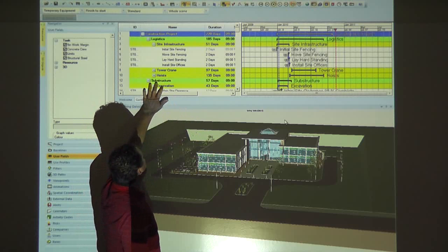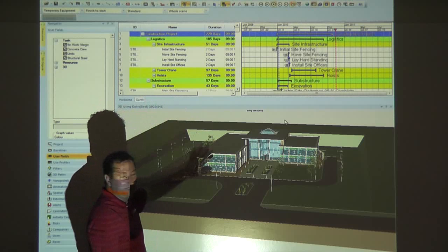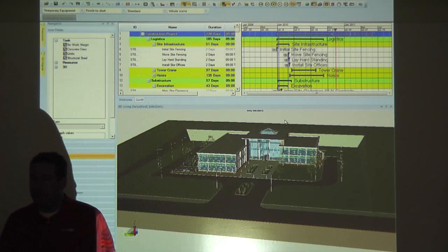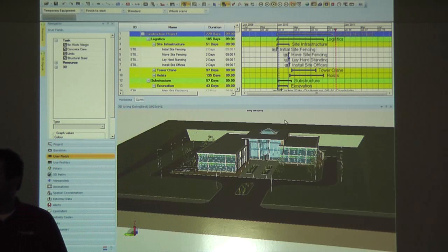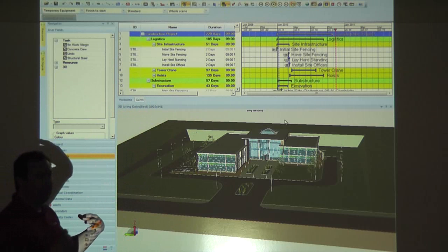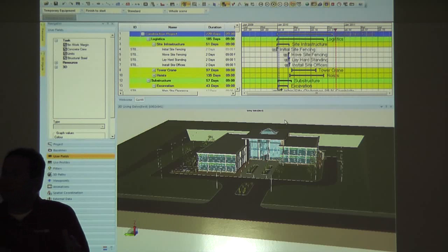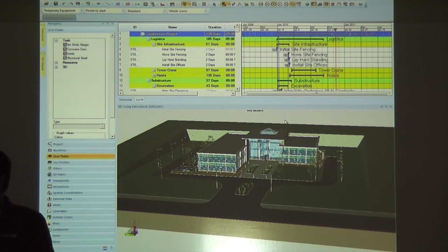The task list would come from SDS2 because inside of SDS2 I would have brought a Microsoft Project task list in and said these columns are sequence 1 columns. So I would go to my task list and say these columns are sequence 1 and then sequence 2 and so on.